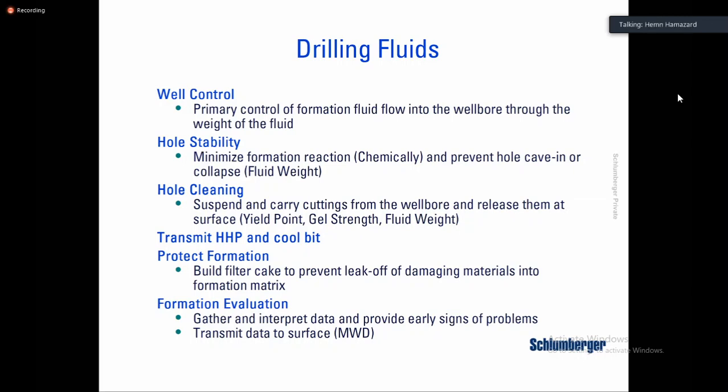And this trapped pressure is mainly created by gas, okay? And the gas, in the majority of wells, is sour gas. That means it's H2S. And if H2S gets to surface, it creates risk to everybody's life on that location and also in the surrounding area.